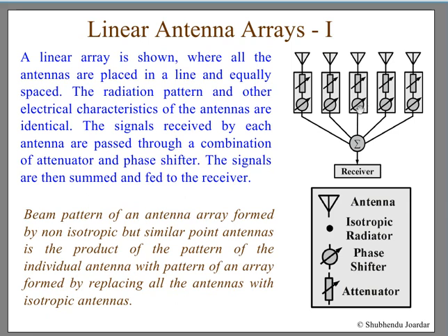So I will start with this. There are several antennas. First, I will consider these antennas to be isotropic radiators. I derive a general expression for the antenna array factor, which is the radiation pattern of the array. That is called the array factor. From there, for isotropic sources, the array factor is computed. After that, you can use the actual radiation patterns, just multiply them, and you get the array factor of your system. This is the general rule that is followed here.